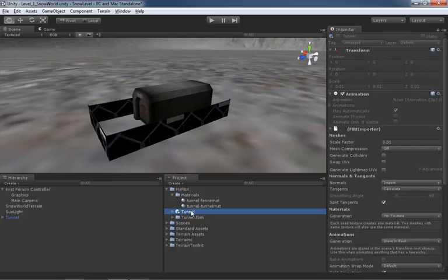Right, this is actually our FBX that we brought in. Now, if we take a look here inside the FBX importer section in the inspector on the right-hand side of your screen, right about midway down, again, depending on your resolution, you'll see a property called scale factor, which is set to 0.01. Even though in Maya, when we exported, we saw a scale factor of 1. Whatever number you saw in Maya is going to be divided by 100 by default when it comes into Unity. It's not the most fun thing in the world, but it's just kind of how it works.